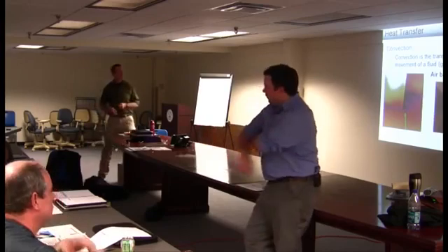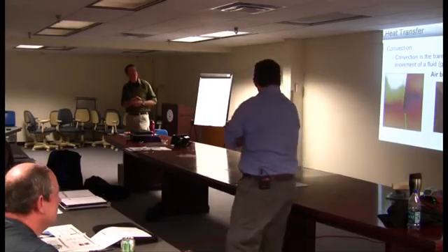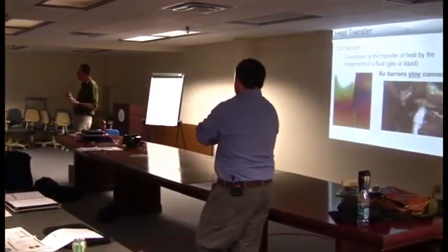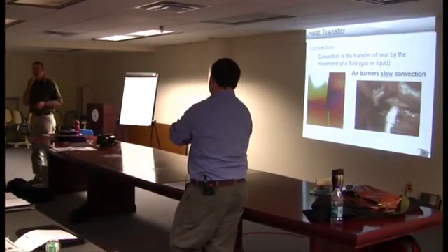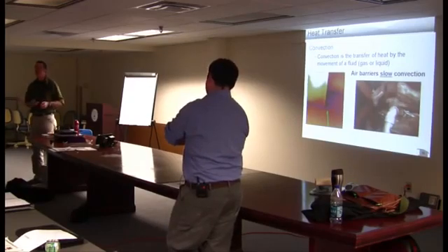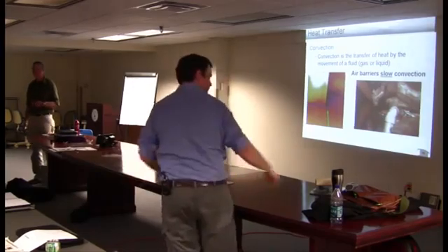So the picture here, again, is showing air leaking under a wall bottom plate, it looks like, and that was, again, a cold sign. And the dirty insulation is telling us that the insulation was acting like what? Yeah, a big filter, right? So the filter effect of the insulation is evident. That's a visual clue that no air sealing had been done, and that looks like a plumbing chase or some sort of plumbing penetration.